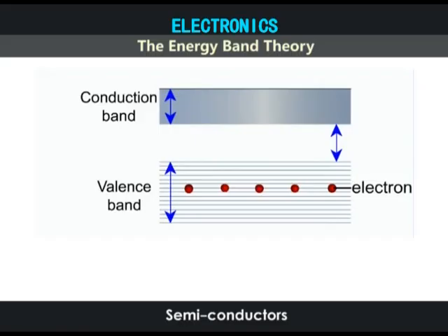At high temperature, electrons excited by heat can gain enough energy to jump from the valence band to the conduction band. When this happens, the electrons leave holes in the valence band which behave like positive charge carriers and can also move freely. When a potential difference is connected to the semiconductor, the holes and the electrons move in opposite directions and are called the charge carriers. Let us see how that happens in their real structures.